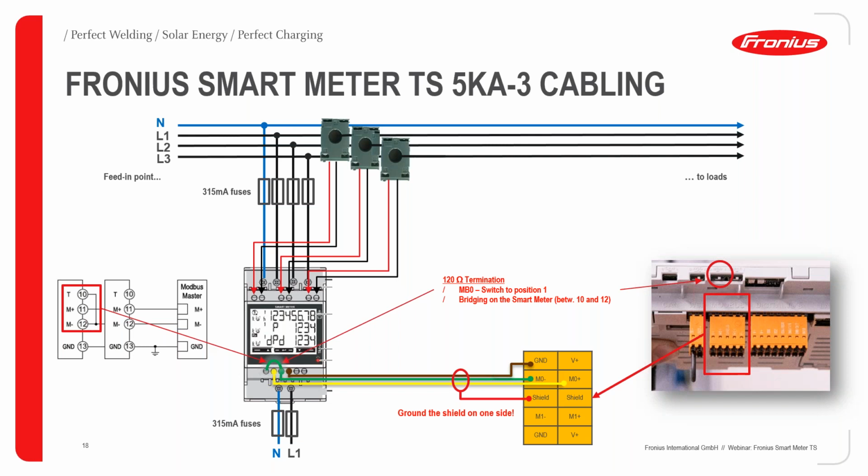Yeah, when we come to the data communication, of course, it's very similar. Again, we have the 3 connection points here, and then the bridging for the 120 ohm resistor, and also on the Gen 24 inverter, of course, it's the same regarding the resistor here.